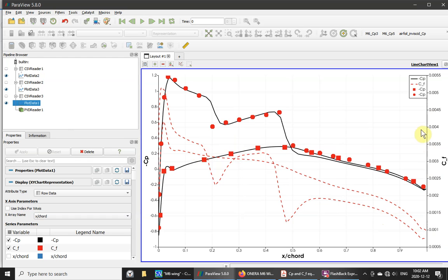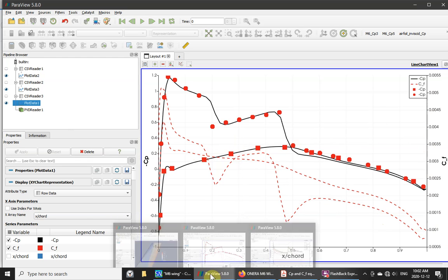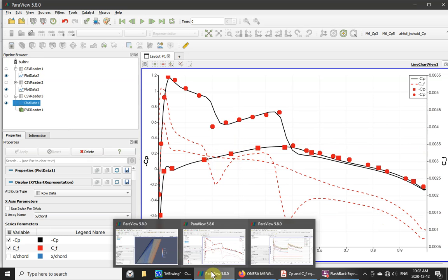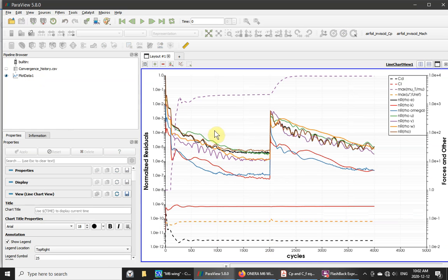And by the time you've finished this video, you should be able to produce other kinds of plots, such as a convergence plot, which is shown here. What you're seeing here is the ratio of eddy viscosity divided by molecular viscosity, and the maximum value of that reaches a constant value on a coarse subgrid of an imported grid, and then also reaches a constant value on the full grid.